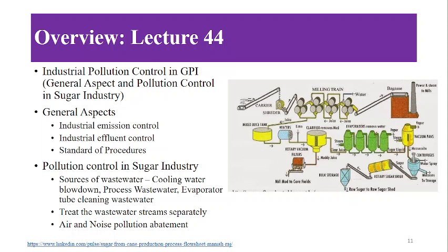So there are four shown here, and this basically increases the concentration of the sugar crystals. Then this concentrated liquid goes into the vacuum pans, where further concentration and evaporation takes place, and from there this massecuite type of liquid is formed, which has sugar crystals as well as the dense liquid, which is molasses.